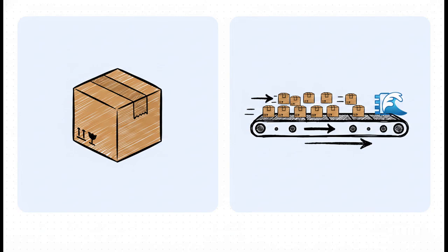The sequencer deals in sequences and sequence items. A sequence item is just a single transaction. Think of it like one single data packet, or just one instruction. A sequence, on the other hand, is a complete set of those transactions that make up a whole test scenario. So, a continuous stream of packets being fired at your chip over and over. That entire stream is a sequence.